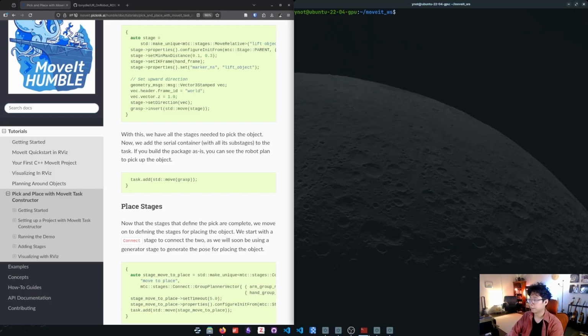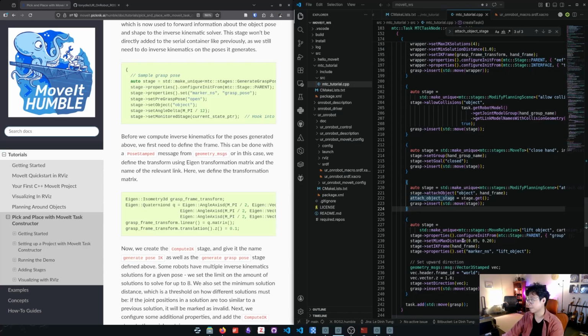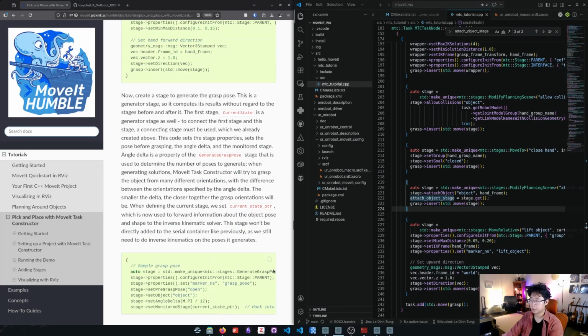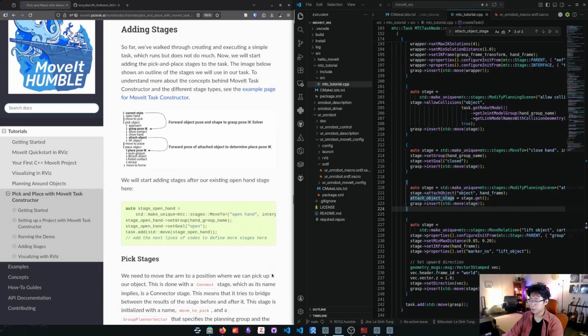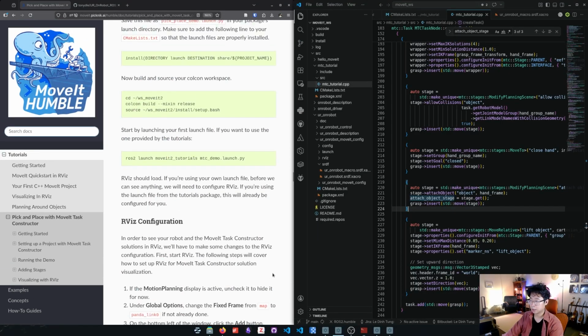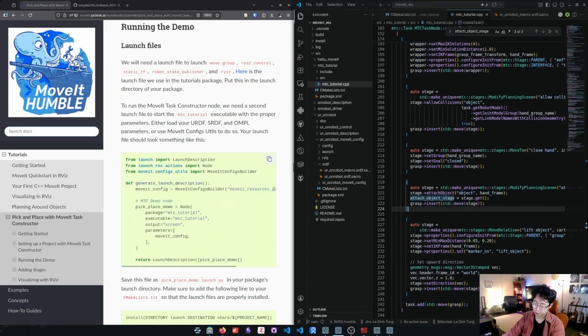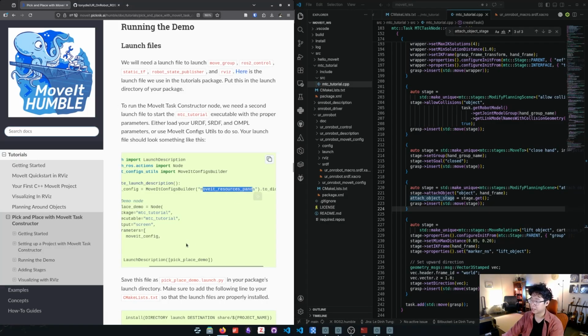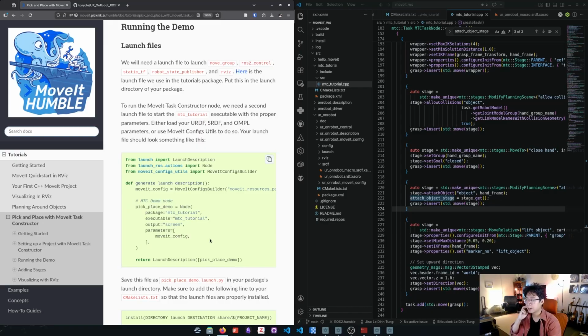This is the warning. Now, before we can actually run this, as I mentioned before, we will need a launch file. So by default, I think they have given us this launch file here, which we can use as a starting point, but this won't be enough because here they already have this MoveIt resources Panda package that will give it the right MoveIt config resources. But since with our OnRobot package, we are constructing the robot description and semantics description every time we launch it, we have to do it a little bit differently. So we have to write a launch file. Let's do that.